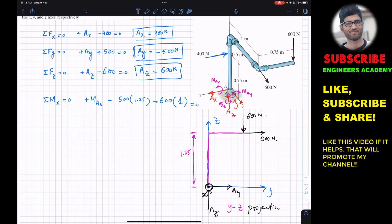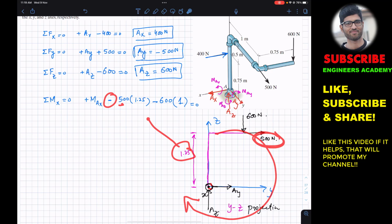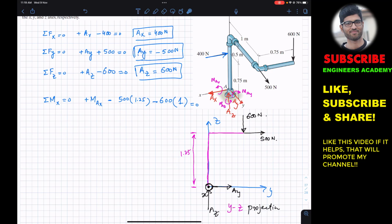If we find the summation of moment about the x-axis, this 500 Newton force is producing a clockwise moment about the x-axis. That is why we have minus 500, and the perpendicular distance of this force from the x-axis is 1.25. Similarly, this 600 Newton force is producing a clockwise moment about the x-axis, and its perpendicular distance from the x-axis is this 1 meter distance. That is why we have this equation.